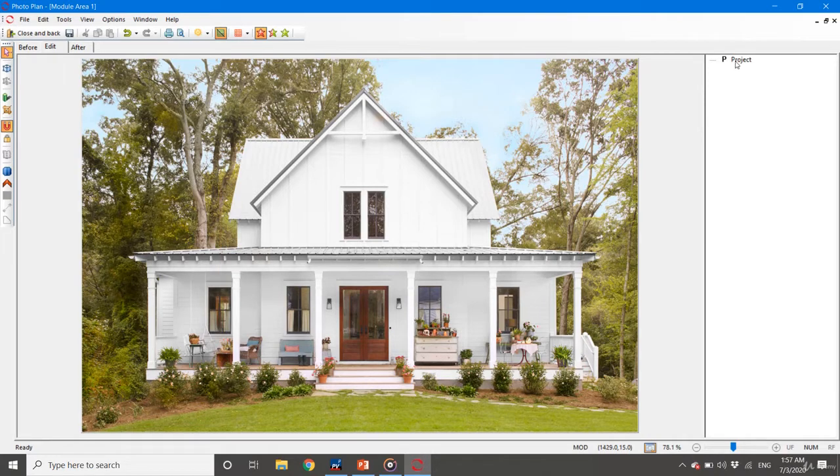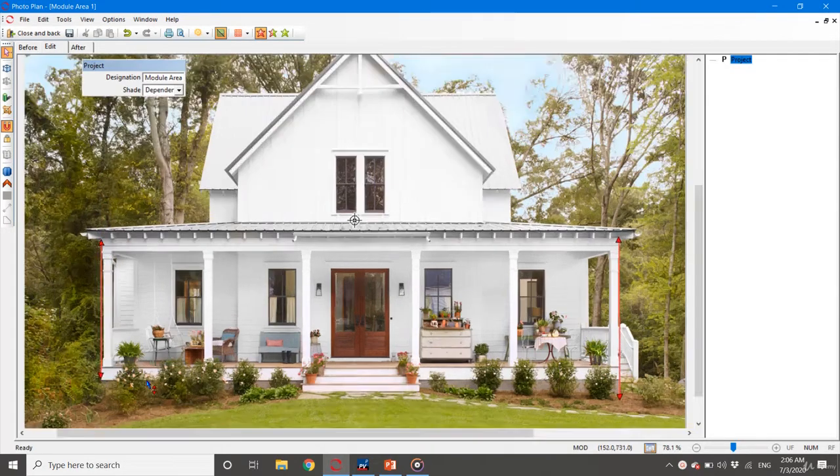When you click here at the window on the right side and select the project or the design, two red lines will appear. The two lines should be placed at two vertical or perpendicular edges in the structure or in the house, as we can see. These should include an area greater than the area of the PVs. When the blue arrows appear, you can drag calculation lines wherever you want. The red up and down arrow lets you adjust the line's length.